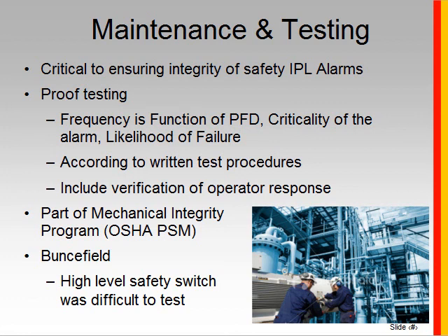Maintenance and testing, of course, are also very important to ensure the integrity of those safety IPL alarms. And the best method, and ideally what you're doing with the testing, is to verify the annunciation of the alarms. You're addressing that failure mode. Ideally, you also want to include the operator's response, if at all possible. Then you're testing the full layer of protection. And of course, safety IPL alarms, due to their critical nature, would probably be part of an OSHA mechanical integrity program.